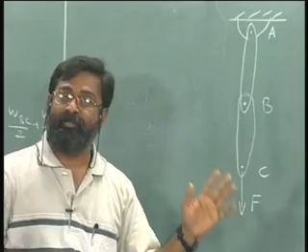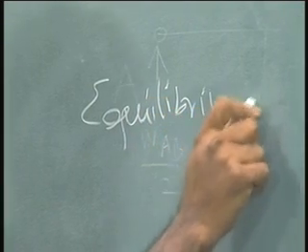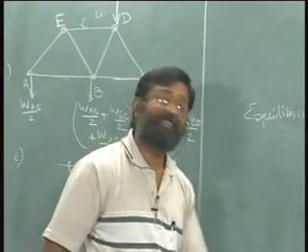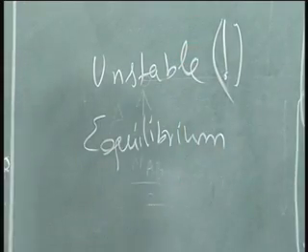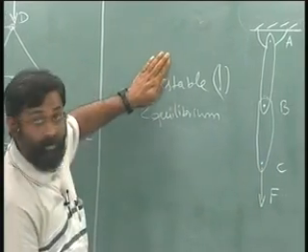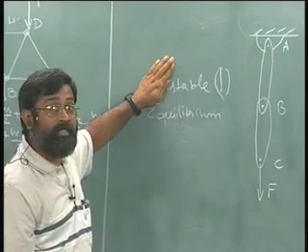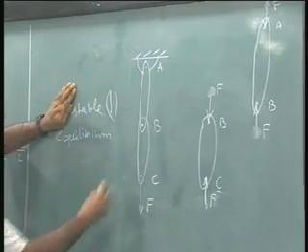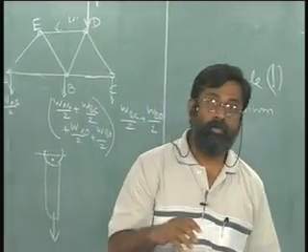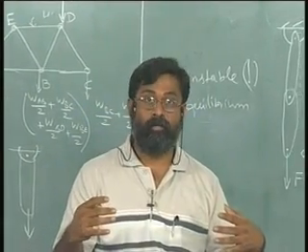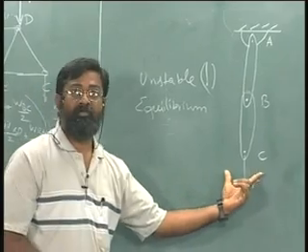Well, is it in equilibrium? Definitely yes, it is in equilibrium. But the problem is it is not in stable equilibrium, it is in unstable equilibrium. Supposing the force is in this direction, there is no problem, it is stable equilibrium. The moment the force is in the upward direction, even though I can solve for the equilibrium, please remember if there is a slight movement sideways, immediately it will become unstable, okay. And therefore please remember that a problem for equilibrium may be to do with unstable, stable or neutral equilibrium, okay. This is a perfect example of an unstable equilibrium, okay.